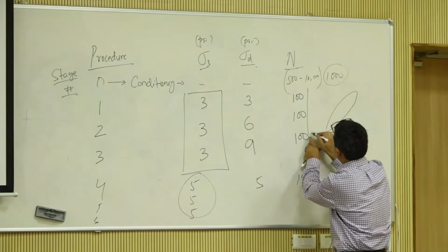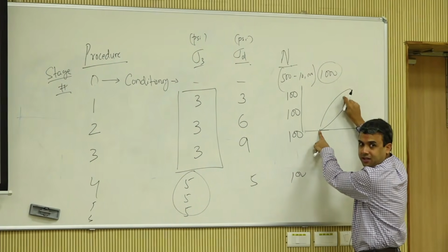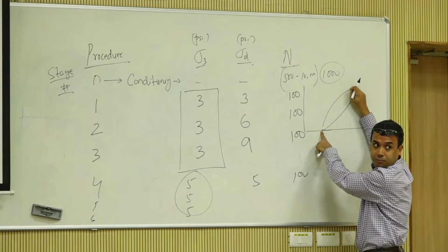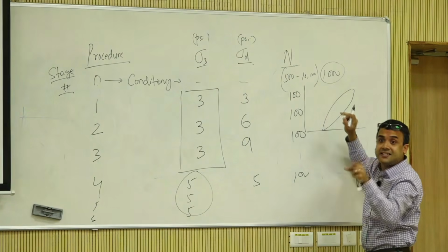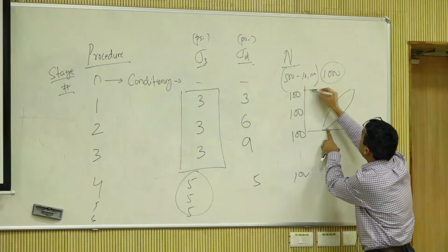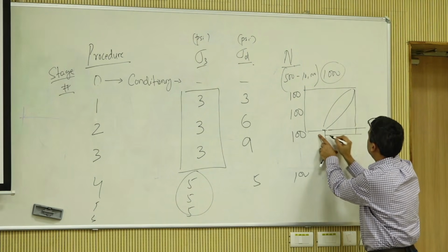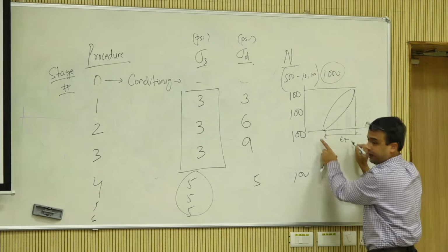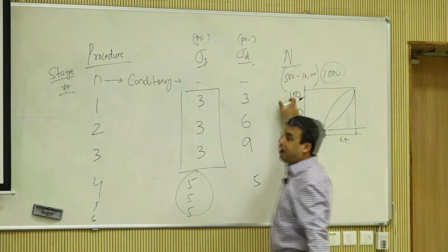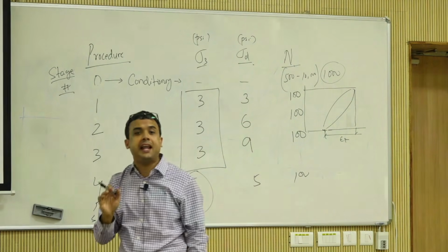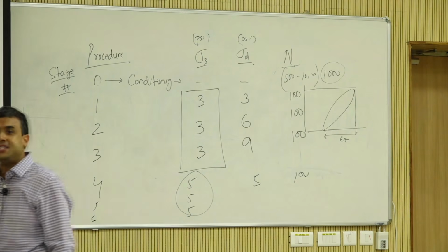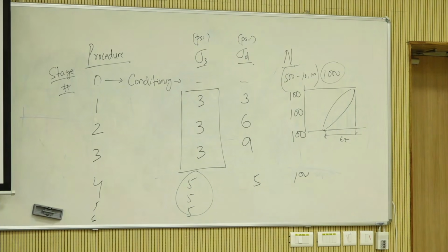I should have the axis here. So you have already moved past, you are somewhere here. Now you are in a hysteretic loop. For every cycle, you have sigma d and you have epsilon r. So for all 100 cycles, you can calculate MR, which is sigma d over epsilon r.